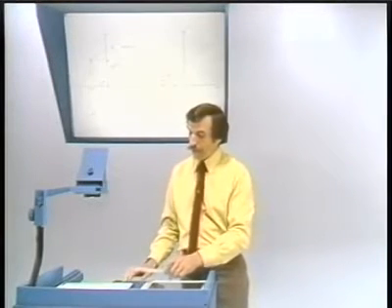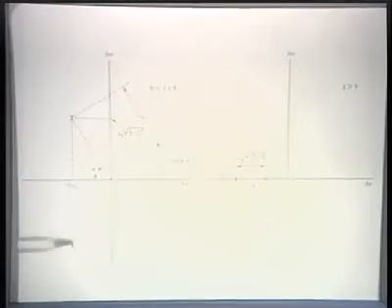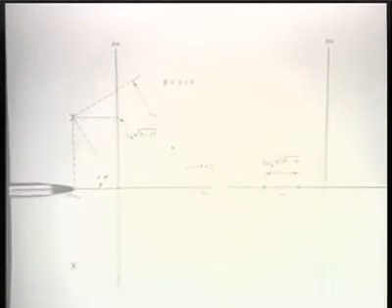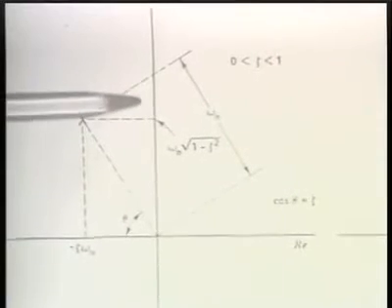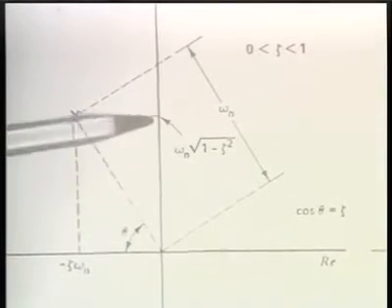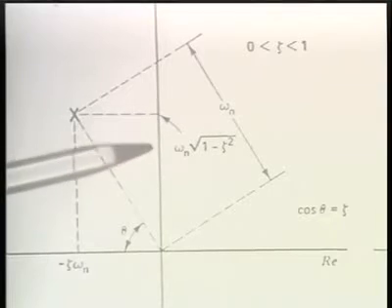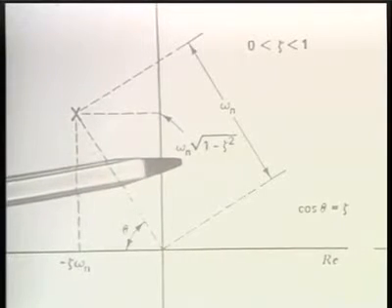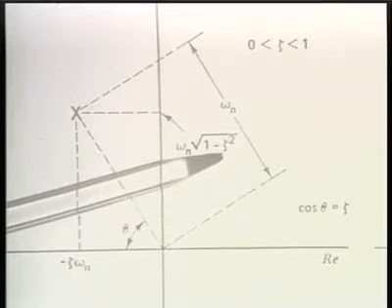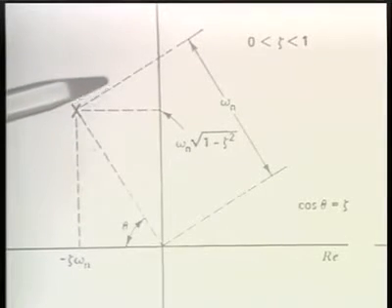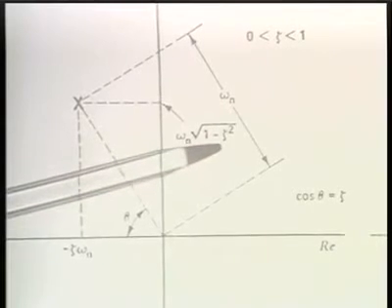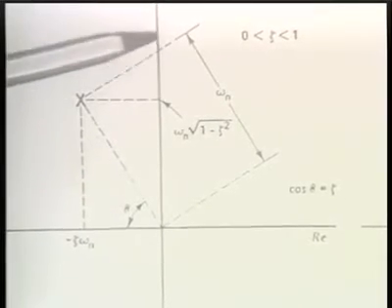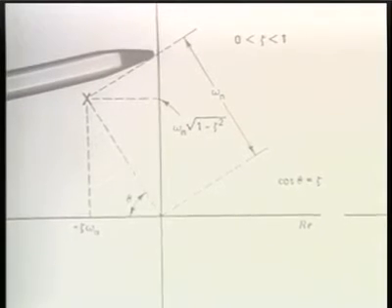And what that corresponds to then are two poles in the complex plane. And they have a real part and an imaginary part. And you can explore this in somewhat more detail on your own, but essentially what happens is that as you keep the parameter omega sub n fixed and vary zeta, these poles trace out a circle. And for example, with zeta equal to 0, the poles are on the j omega axis at omega sub n.